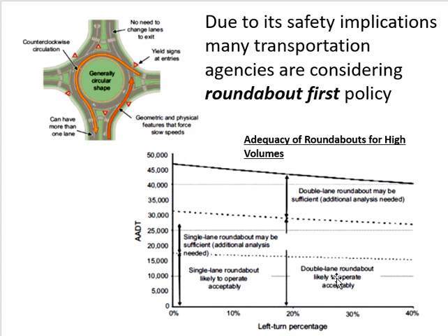Left turning means you will come from here and you will take this exit, right? So most of the people are rotating 3/4 of the roundabout. So then we provide more lanes. Most of the people are just going straight and right. It's not a problem. But there are many people, not most, many people who will be using almost the entire roundabout, so it's better to give them more lanes. So this is it.